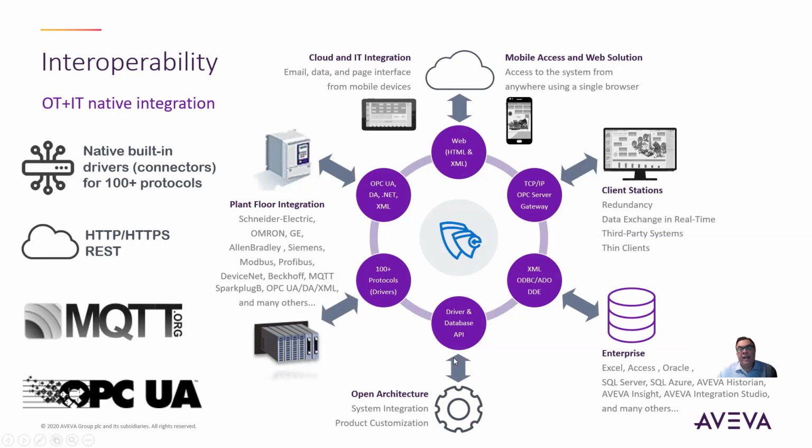And if you have the need, you can develop your own toolkit or your own interaction with our tags, and develop your own drivers as well. But supporting REST APIs, supporting different drivers, OPC built in, and again, OPC is not necessary. We have over 100 drivers built in. You can probably get to the PLC or the device or the thing that you need to communicate with. So that's making it kind of easy as you go.